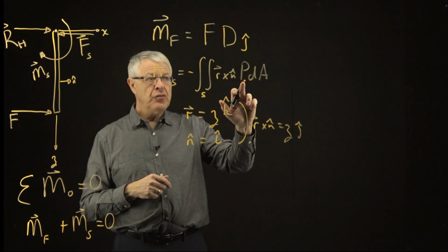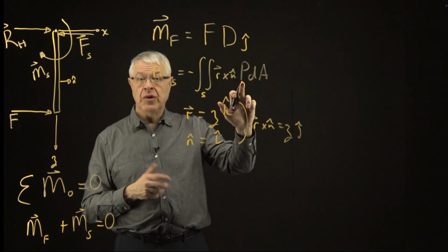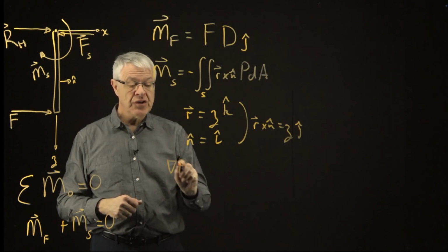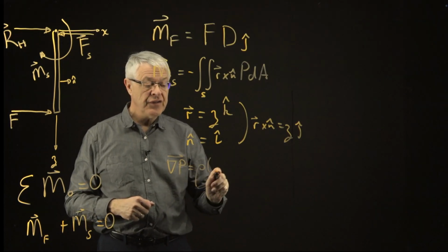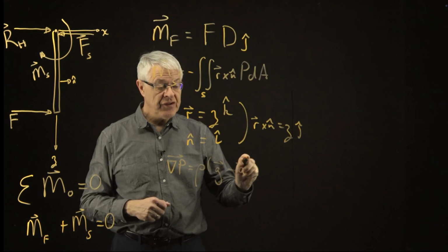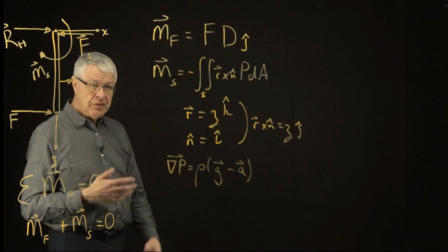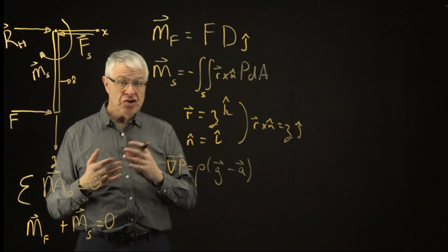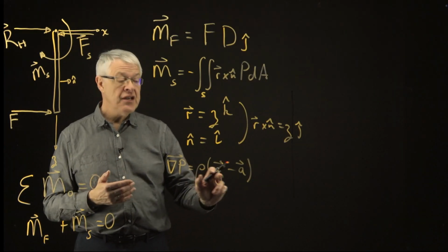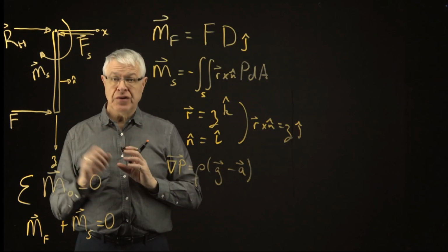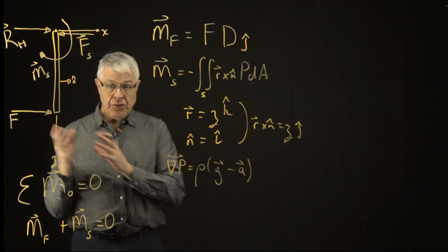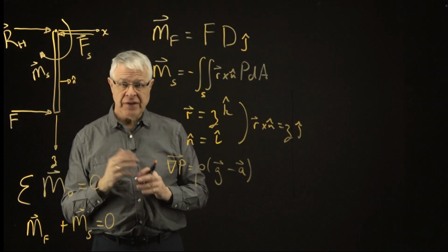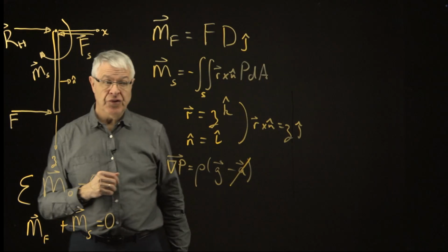Now, the next thing we want to do is talk about the pressure distribution. Well, pressure distribution is going to come from the basic hydrostatic equation. So our starting point to get the pressure distribution is our basic hydrostatic equation. So this tells us the pressure gradient for a fluid in a hydrostatic state as a function of the local acceleration due to gravity and any overall acceleration that there is in the problem. Well, realize there is no overall acceleration here. This submarine isn't taking off from a stop or anything like that. So this acceleration is 0 in this case.